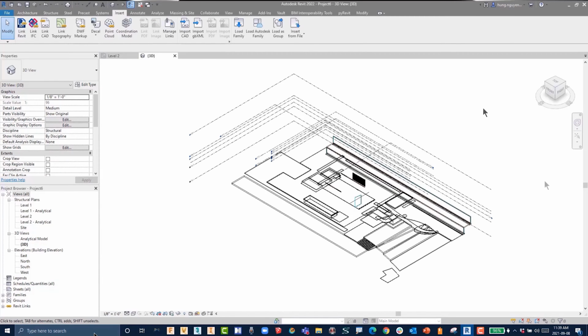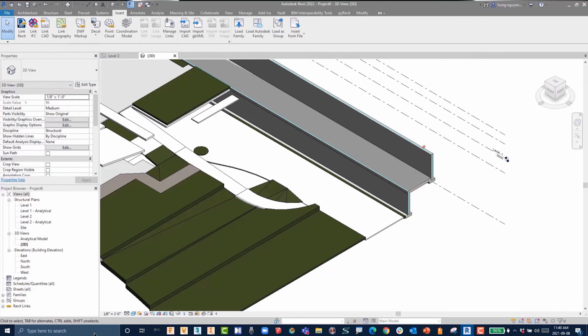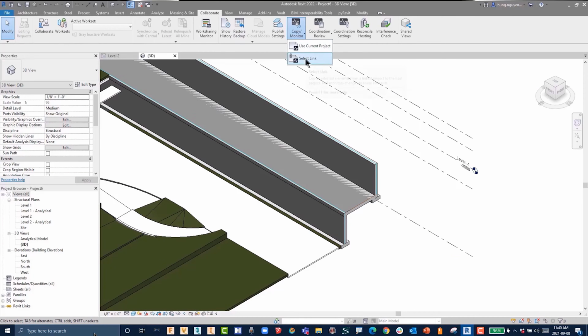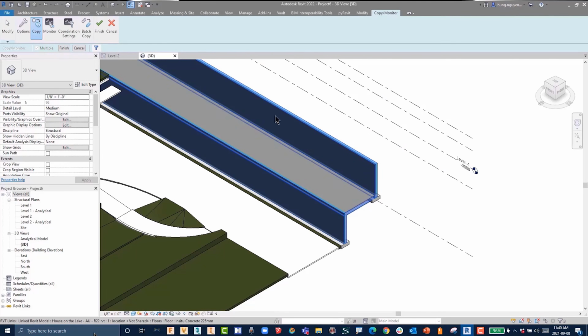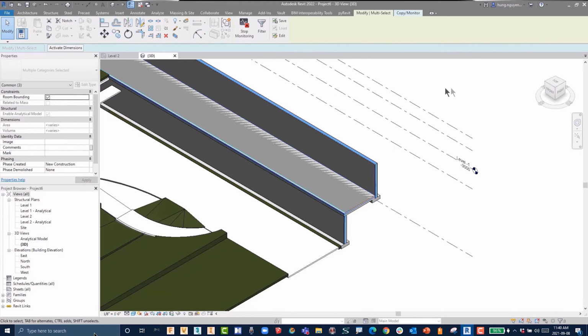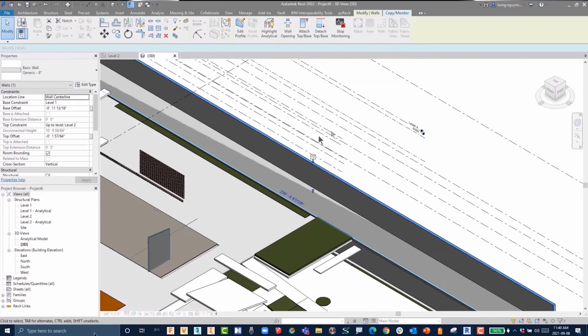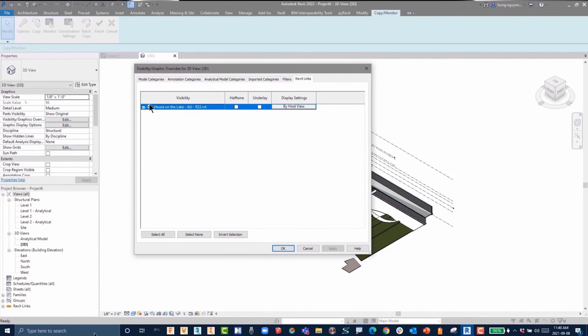And now let me show you the three walls in the back that I need to do the analysis on. Basically, those are Revit architecture walls, and I'd like to copy and monitor the walls. So you copy and monitor and do a multiple copy for the walls and finish the task. And now just double check everything, and I see it actually monitors Lina's model. And about time for me to turn the link off.